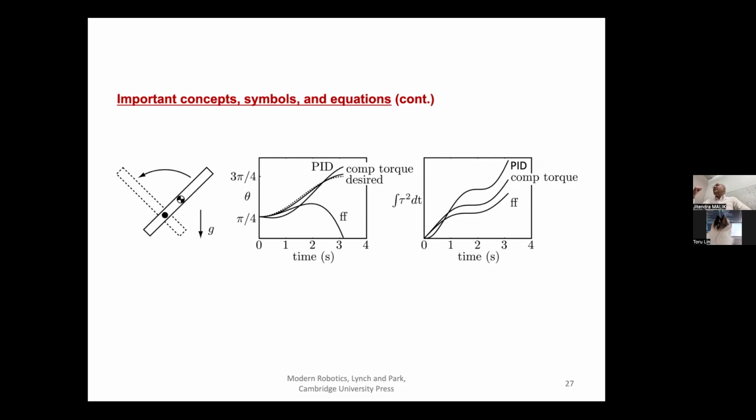So that's like my first example for driving a car on the road. You pick a certain throttle angle, and that's it. So that's the pure feed forward. FF is for pure feed forward. Then you can design a controller which is based on just error measurement and doing the right thing. So that's the PID controller.